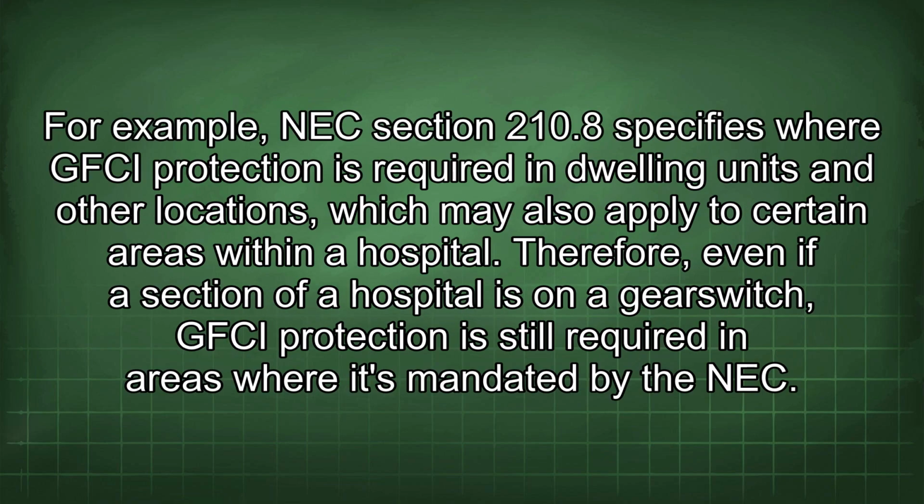For example, NEC Section 210.8 specifies where GFCI protection is required in dwelling units and other locations, which may also apply to certain areas within a hospital. Therefore, even if a section of a hospital is on a transfer switch, GFCI protection is still required in areas where it's mandated by the NEC.